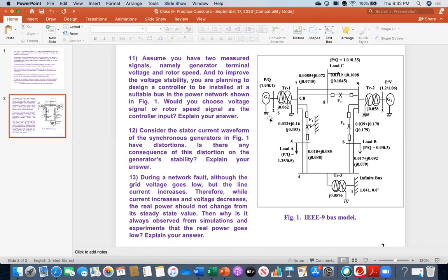Because those higher frequencies will cause higher reactance and higher reactive power. And again, there will be a voltage stability issue. Therefore, this distortion problem will also cause, for example, your prescribed voltage here is 11 kV, and you are measuring the voltage and getting a fairly low value. It looks like there is no short circuit, no open circuit, nothing happened. The network is fine, but still I am getting a low value. What is the cause? That distortion is the cause.